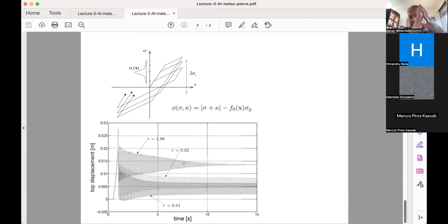Typically, again, this is easy to explain by probability, because if you have a composite material which is heterogeneous, that means from one point to another, the material behavior might be changing. In a small structure, you're likely to be homogeneous. In a very large structure, you might have weak spots, either initial defects or defects induced by the loading. And these defects are prone to producing fracture much faster than when you have no defects. So the bigger the structure, the bigger the uncertainty about these defects.